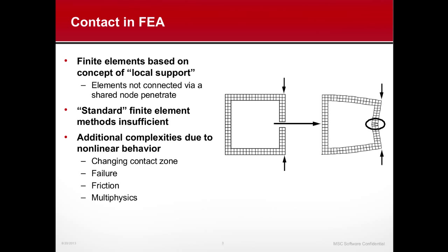Finite elements are based on the concept of local support, whereby the elements are aware of only the connected nodes. And the elements that are not connected by a shared node can penetrate as they're not aware of each other. And so the standard method itself needs to be adapted to ensure non-penetration of all the elements and nodes.